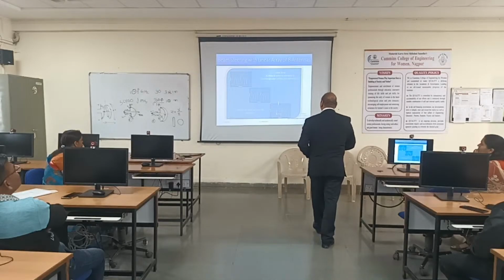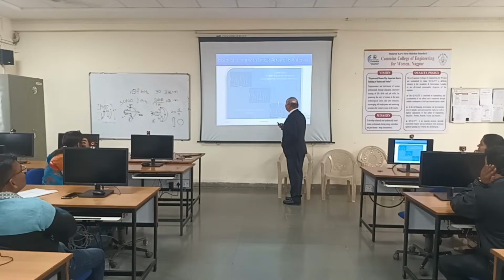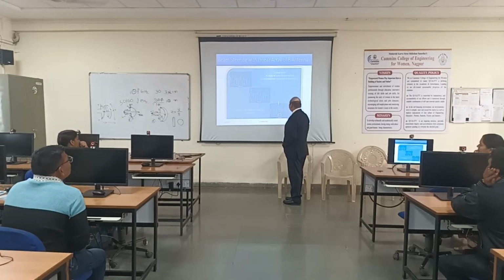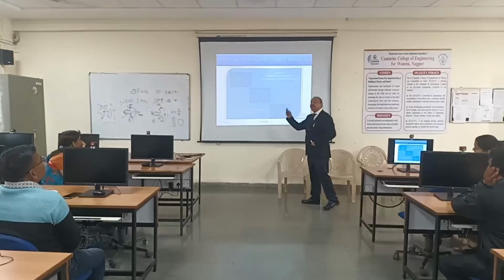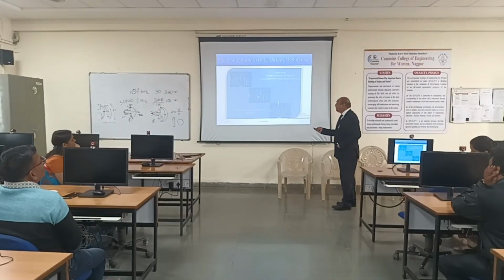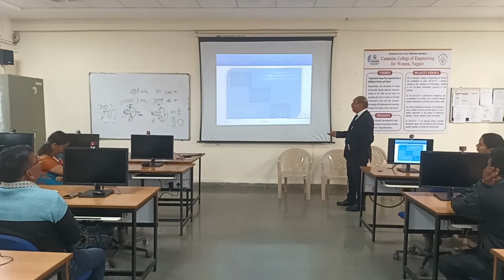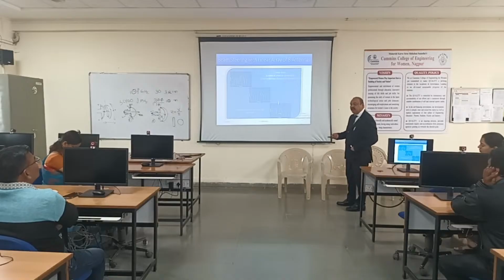And here the beam is maximum at, I think, 15 degrees. This now becomes 30 degrees. This is the way you can shift the phase. By changing the phase, you can shift the beam accordingly. By selecting the delay, we steer the main lobe in any desired direction.